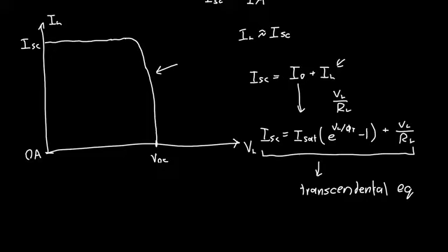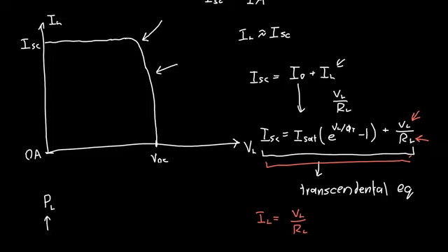We have to solve this numerically. If you plug in different values of RL, you can solve this equation numerically for VL, and then you can figure out the load current by saying it's just VL over our resistance value RL. If you plot enough values of RL, you'll start to generate this curve. Now, one last thing: how do we maximize the power to our load?